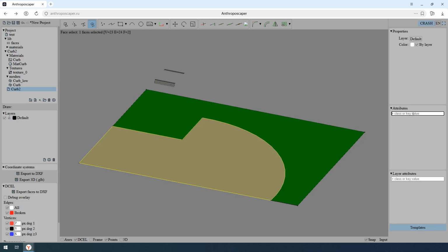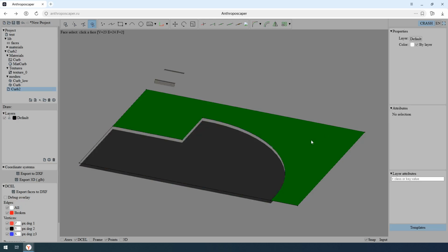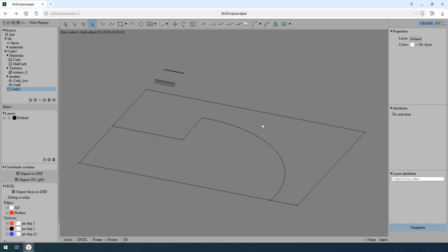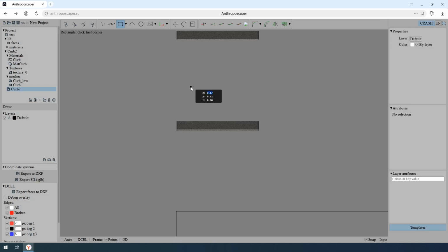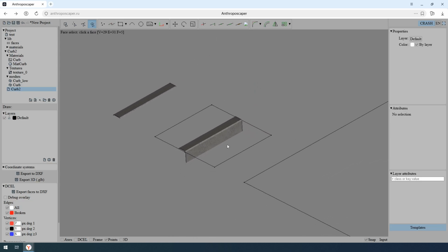On the faces of the test scene, I assign the classes, grass and road. Now the template itself. Its foundation is a closed contour split by an internal segment into two faces. I draw a rectangle, then run a segment through it, the edge along which the template will be tiled. Precision matters here, so I use coordinate input. The curb mesh is modeled from the origin and is 1 meter long, so I set the edge segment the same way, from 0, exactly 1 meter long. Then the geometry matches the template's axis 1-to-1, with no adjusting.